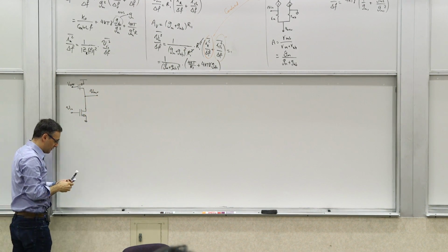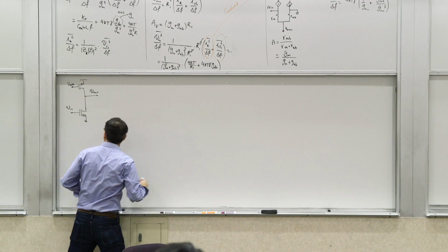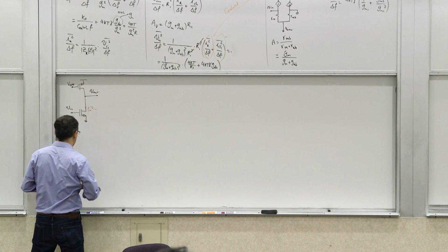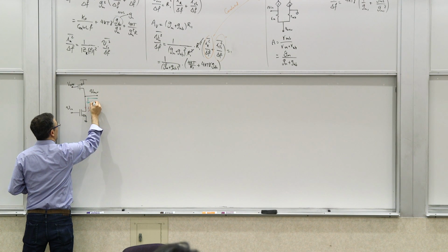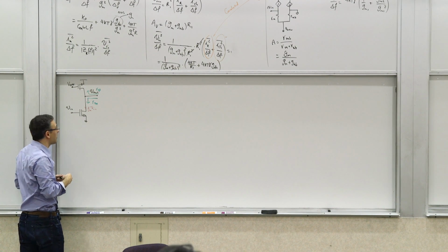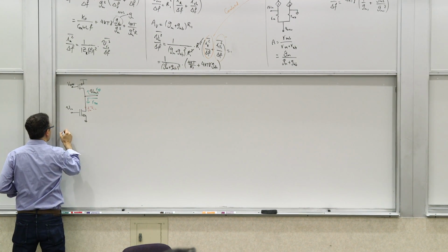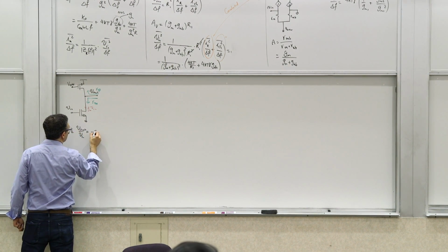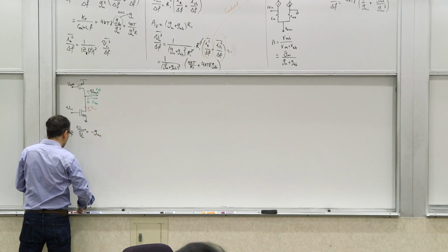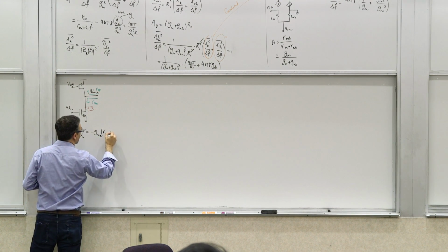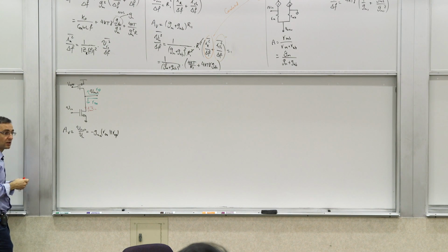What is the gain of this thing? Well, if this is V in, then what comes out is GM V in. From a signal perspective, what is the resistance on the output? It's RON, and looking up, you see ROP, so it's a parallel combination of those things. So the voltage gain, AV, defined as V out over V in, is negative GMN times RON parallel ROP. These are calculations we've done a lot before. So this is the voltage gain.